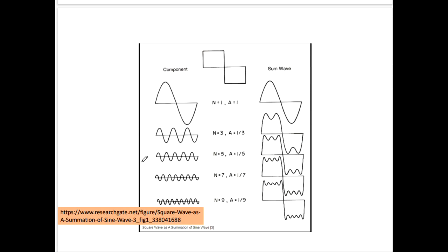Okay, and this is just another example of Fourier analysis. This time we're building a square wave. So we have a fundamental, and then we have a third, and a fifth, and a seventh, and a ninth. We don't always need all the harmonics. This time we're adding odd harmonics: the third, the fifth, and the seventh. There's no even harmonics in here, like 2 and 4. That's another way we can do things. We can skip harmonics when we build things.